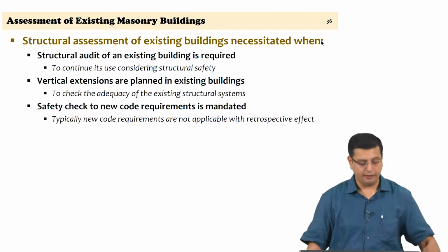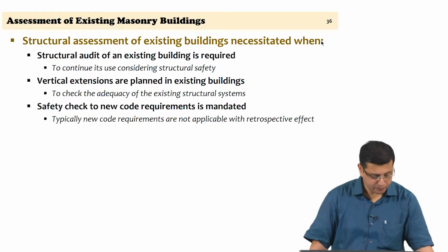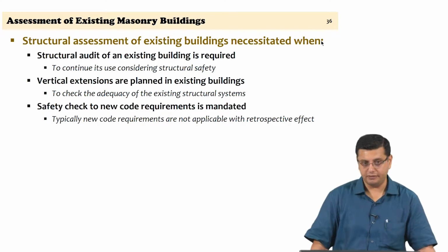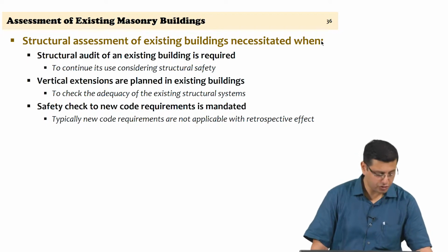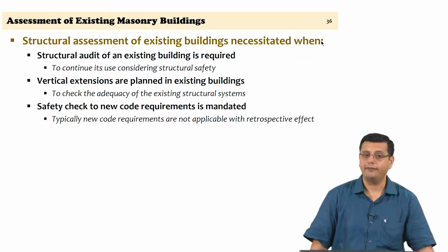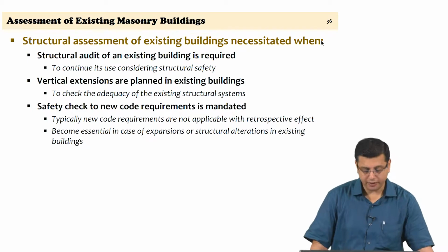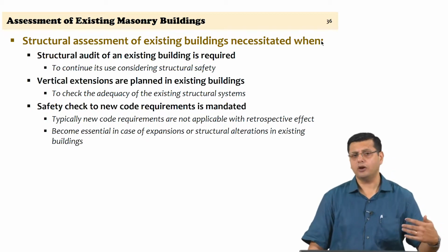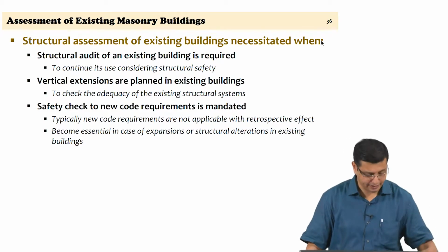So this is typically not done, but when you are looking at structural safety, it might so happen that to ensure particularly seismic safety, you might have to do some retrofit of existing masonry structures, and that would depend on existing retrofit programs in the country, in the territory.